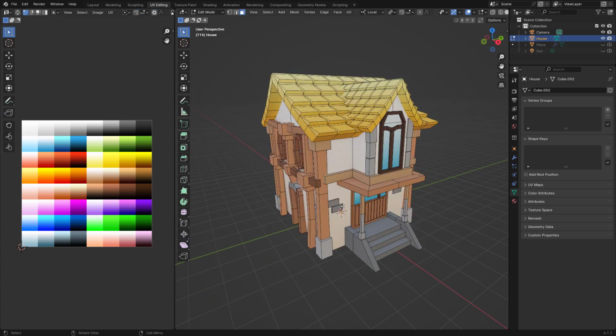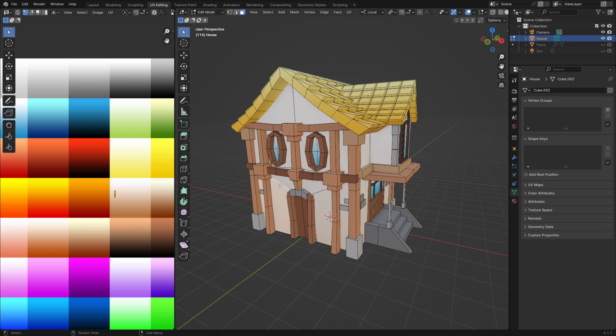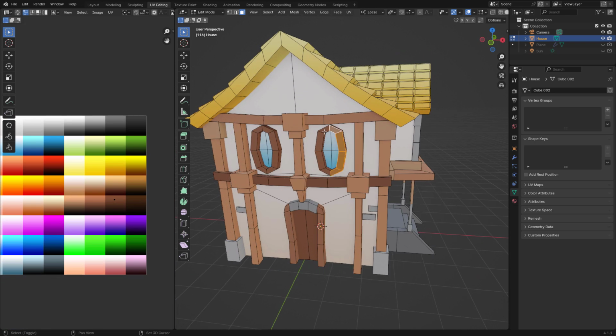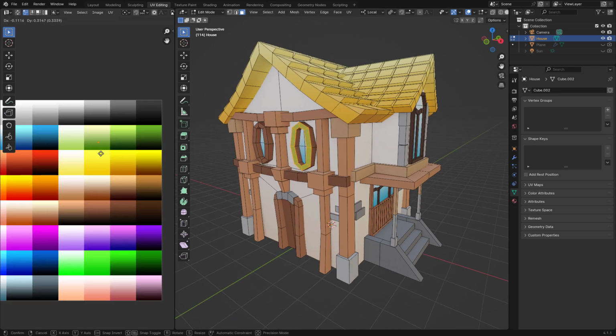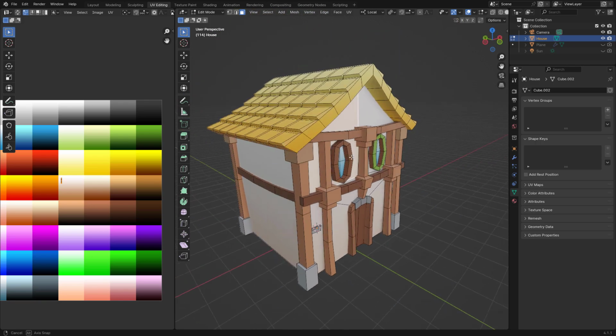In this model, you can notice that in some cases I reduce the coordinates to 0 to obtain a flat color. I only reduce to align the UVs to represent a gradient, but here in the color of the frame, you can notice that all the faces point to the same UV coordinates, so I can change the color of all faces at the same time.